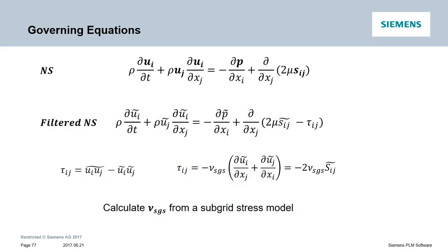So mathematically, one starts by filtering the Navier-Stokes equations to obtain the equations for the larger scales. And while doing that, we immediately realize that the non-linearity of the Navier-Stokes equations will prevent us, once again, from getting an exact closed equation for the filtered variables. And again, a term similar to the Reynolds stress term is produced, and this needs to be modeled, in this case known as subgrid stresses.